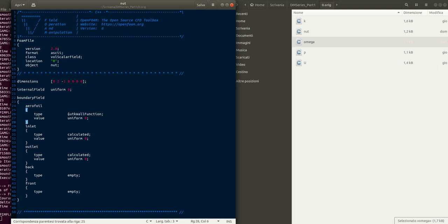And if we wanted to specify a value which is 0, if we did the calculation and did not use the wall function, we would use in OpenFOAM 8 the nutLowRe wall function, which basically just computes the y plus, but lets the user specify the value.